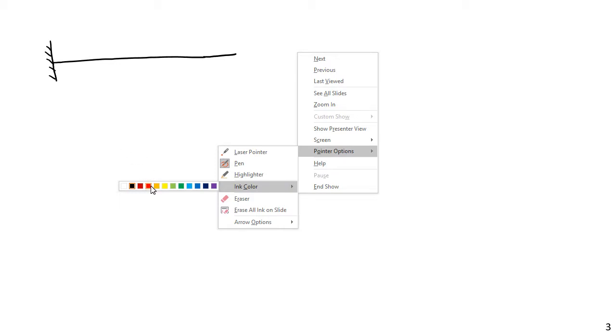The loads here, I'm going to have first a distributed load. This one may look familiar. A distributed load of 2 kips per foot. Then a downward point load of 10 kips at the end of the distributed load. So we're going to keep things relatively simple by having only one discontinuity point here. 10 kips, then we're going to have a 40 kip-foot moment, or a couple, at the end.